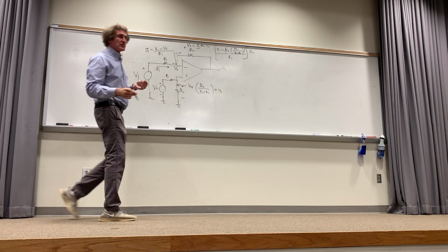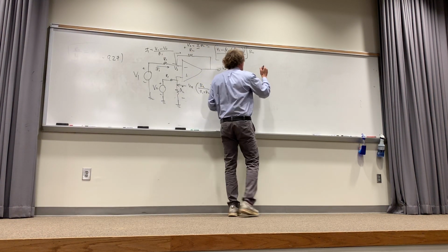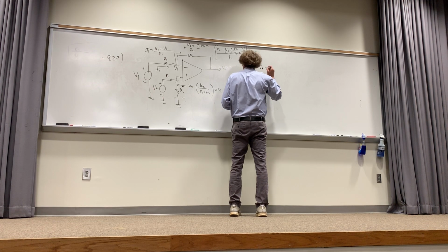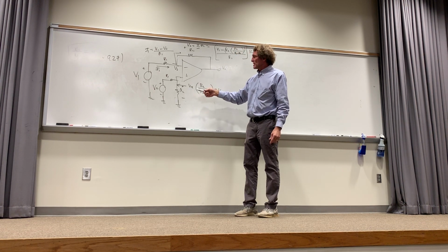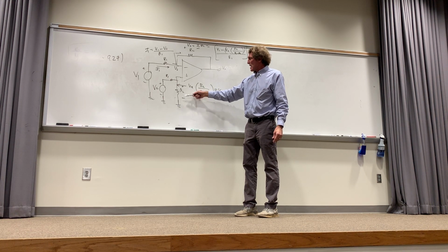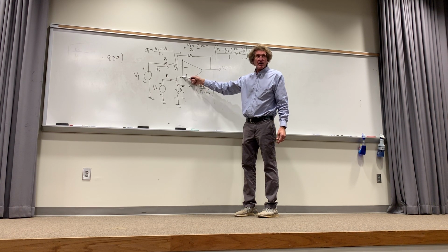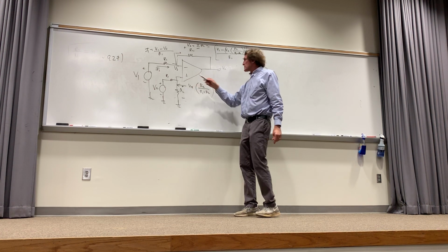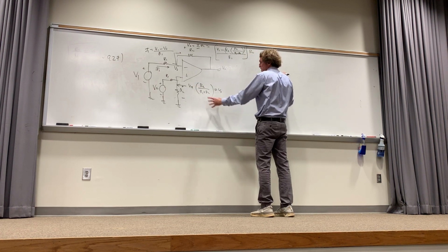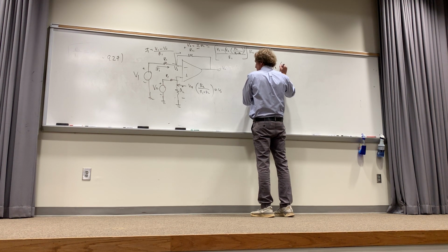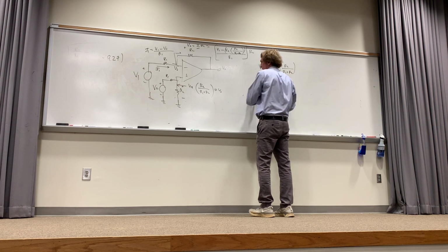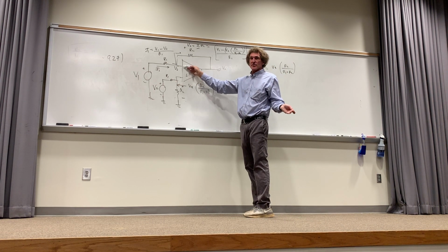Now what would the output voltage be then? Take a look. Well, now, follow me. You can do this several ways. If I come this way, right, I get an increase of V plus here, correct, class? Right, so I'm going to have V plus, and V plus is this. If you want me to write it down, I will. So I have V2, right, times R2 over R1 plus R2. That's this voltage. No voltage difference, right?